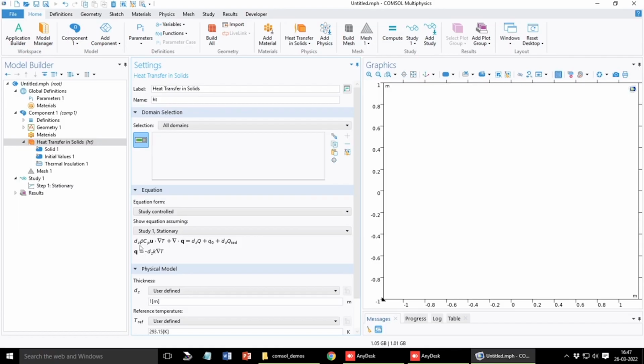Of course, for the case of solids, this U is equal to 0. So, this is the general purpose convective diffusive heat equation. So, there is no component of U, it is only grad dot small q is equal to 0, and if you insert the heat flux or thermal conductive flux in terms of q, it will give you the Fourier equation, which will give you the Laplace equation finally.